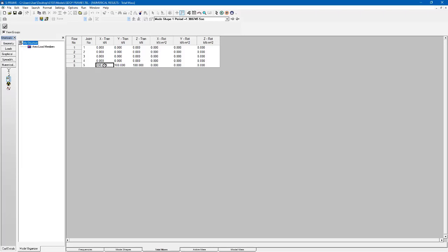So why is this important? Well, basically the z load that I applied, when it was converted to a mass, was converted to a mass in all degrees of freedom. So in the z, y, and x degrees of freedom. And in the x direction, I also had that lump mass that was applied. So that's been added to the mass in that model.